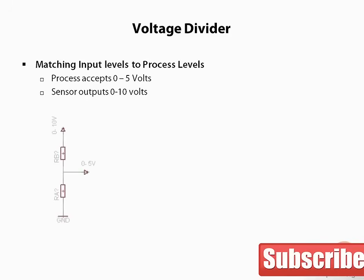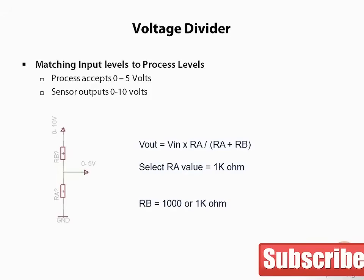Here is our circuit diagram, again, except Vin equals 0 to 10 volts and Vout is equal to 0 to 5 volts. Looking at our equation again, Vout equals Vin times RA over R total. Since our equation is ratiometric, mathematically it doesn't matter what the exact values of the resistors are, only the ratio of them. So for now, let's arbitrarily choose RA is equal to 1 k ohm. Then solving for RB, it is also equal to 1 k ohm.